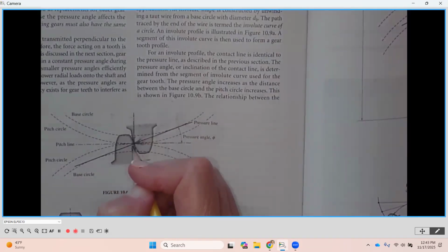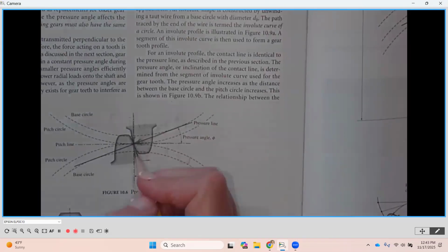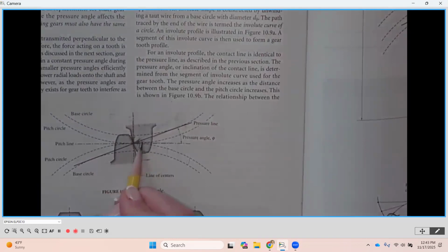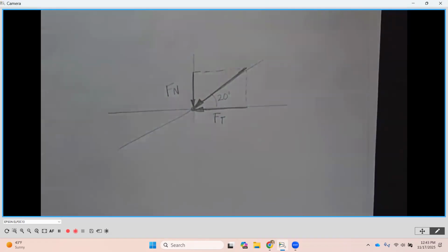And so what can happen is two things. Number one, it's always going to hit on that surface, so it's going to cause pitting or cracking on that surface. Over time, it can cause fatigue on the surface and break it away. But another thing is if this gets too high of a force, it's going to bend that tooth over. It can actually shear it off. That can happen with gear teeth, as we know. So that tangential force is the one that usually dictates our design.